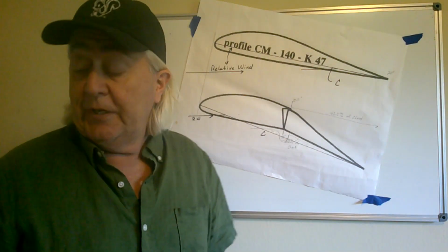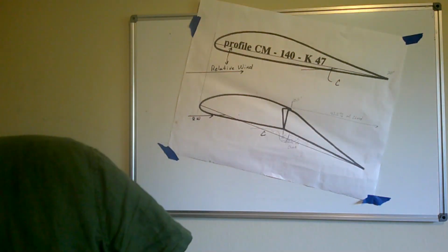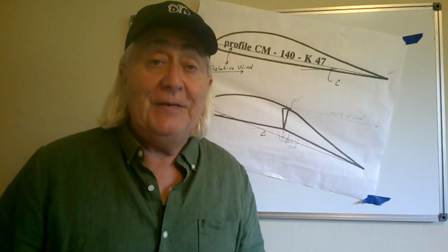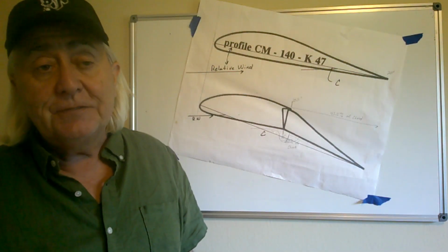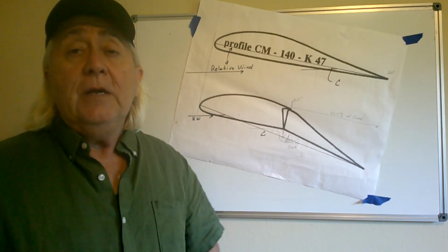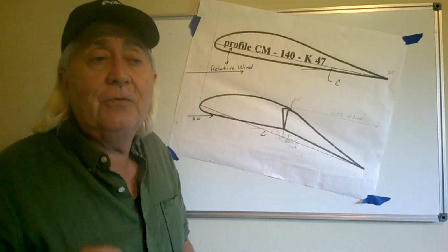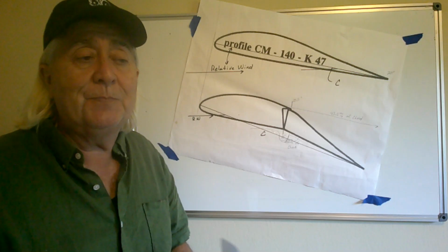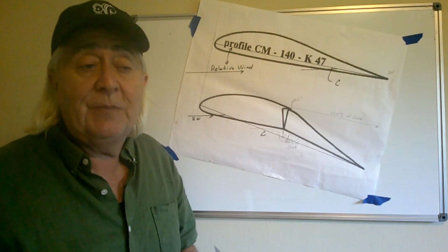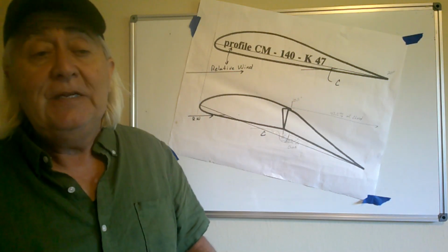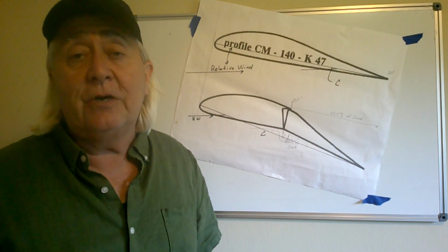You've stalled the wing. And to drive this point home, I know it's a mundane answer. What caused this crash? It stalled. Everybody likes to hear all those fancy separated flow and this, that, and the other thing, and specialized flying wing problems about flaps and pitching moments and elevons, and yeah. This was a stall.